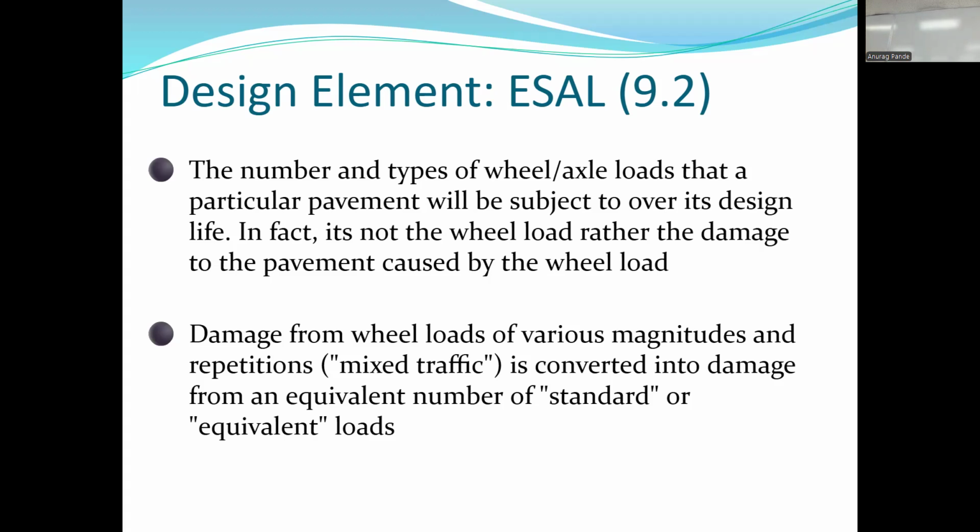And in this class, we are not actually going to design the pavement. We're just going to learn, if you're given a certain amount of truck traffic on a road, how do we estimate the equivalent single axle load for that? And then once you know that equivalent single axle load, you can learn to design the pavement based on that number in CE 429. So CE 429 is your pavement design class, which is where we pick up that discussion. Based on ESAL, you determine the thickness of the pavement and things like that. So that all happens in CE 429.